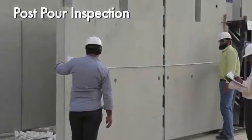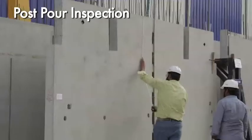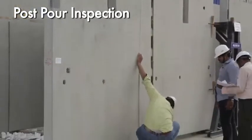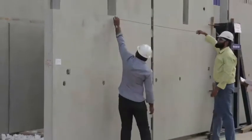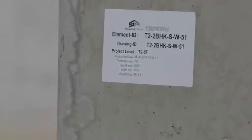Post-pour inspection must be carried out for each panel. Inspection includes dimension of the panel and location of inserts. Defect-free panels are approved by the site QC. In case the defects are beyond specified tolerance limits, panels are rejected.